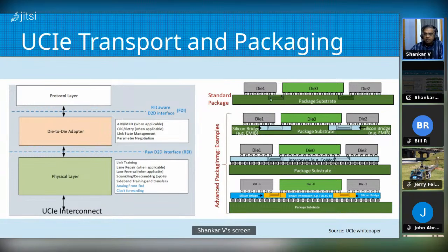Similar to PCB traces, you have wires connecting signals on one die to the other die, and then for the other ones, it will feed through to the bottom, and you will have the pins or bumps at the bottom. And so this bottom part would attach to your motherboard. So some of these signals from each die would feed through to a motherboard connection, and others will be used for these die-to-die connections.